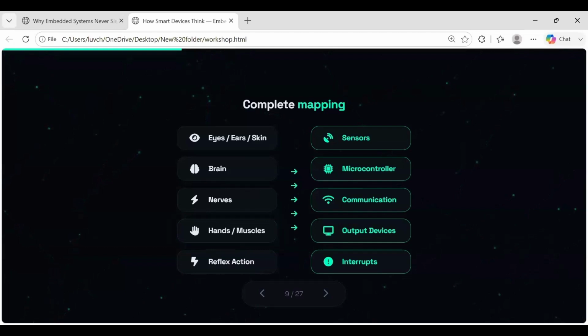Quickly, ultrasonic sensor, LIDAR. My dear, every sensor in this whole world will convert its data in terms of voltage or current. And the voltage and current is understood by your microcontroller. That we will come across in just a few minutes. Right. So this is the very first thing you have to be very, very clear about. Unless you know the principle, the conversion of every sensor in terms of voltage or current, how will you interface a sensor? Try to understand.